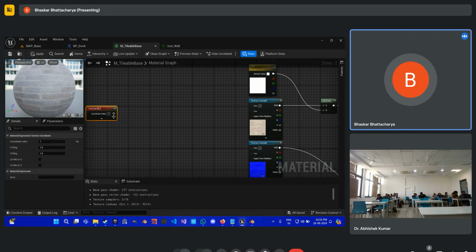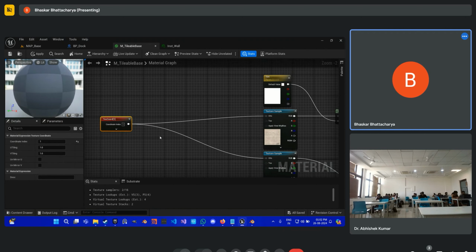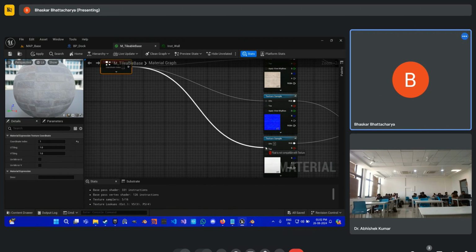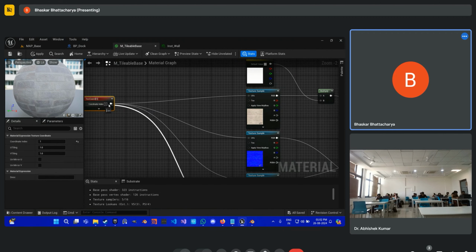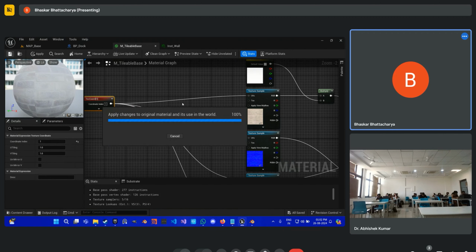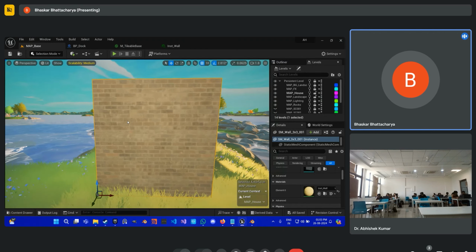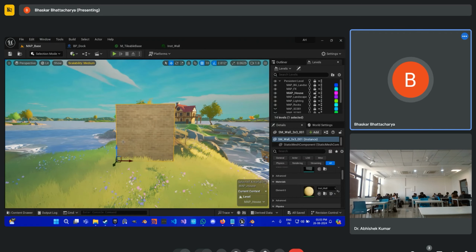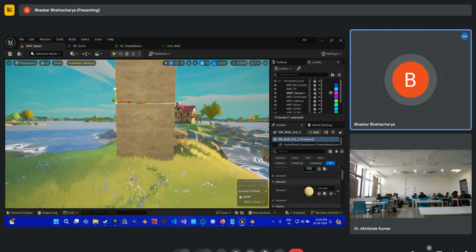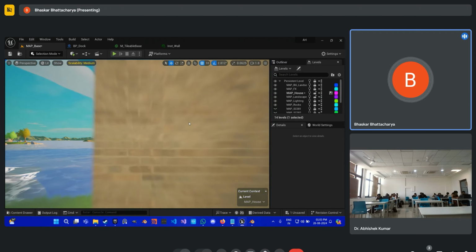So I'm passing a coordinate index of 1, and I'll connect this to UV for all the texture maps that we have. Once we have saved this, you will see this has changed because now it is targeting the correct UV channel, and our asset is properly tileable.